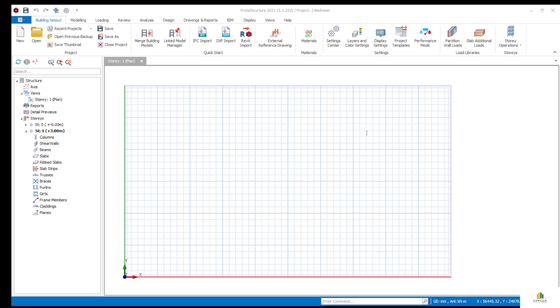Because we want to add one, we delete the number from there, or you type the number. So we want to add one story to it, right? Then you click OK. You see that the OK is like a mark in green. You click OK, then it will add the story. So now I have my story 0, story 1, then story 2. So now is a two-story modeling that I'm doing, a sample model.